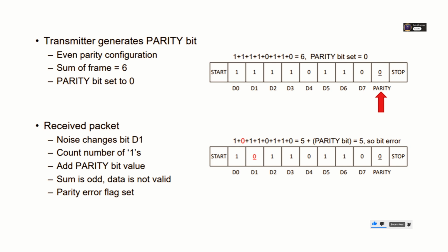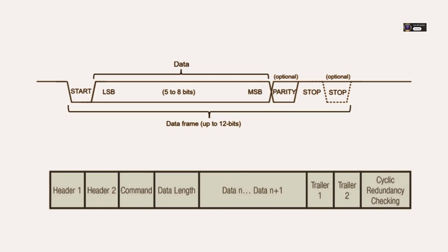If an error is detected, or if maybe a whole chunk of data just gets lost, how do you typically recover or even notice the loss? Good question. Recovery often involves a few layers. If an error flag is set, you might just flush the receive buffer to discard the potentially corrupted data and wait for the next valid start bit to try and resynchronize. For more robustness, you often build error handling into your communication protocol on top of UART. This might involve retries. The receiver asks the sender to resend the packet if it detects an error or doesn't receive it within a certain time.